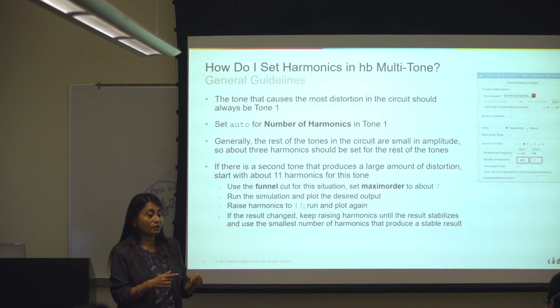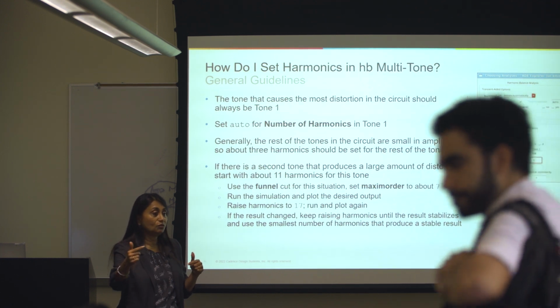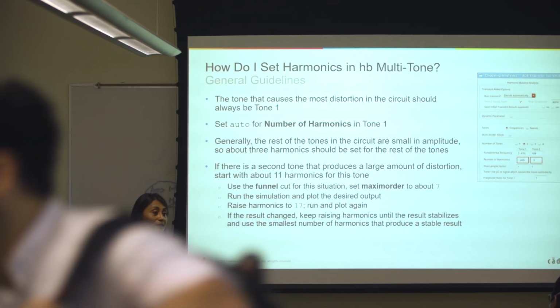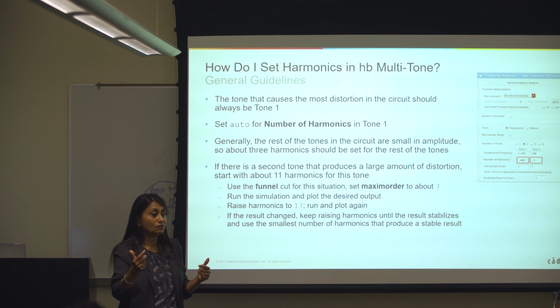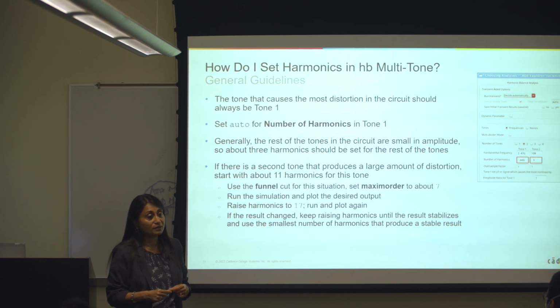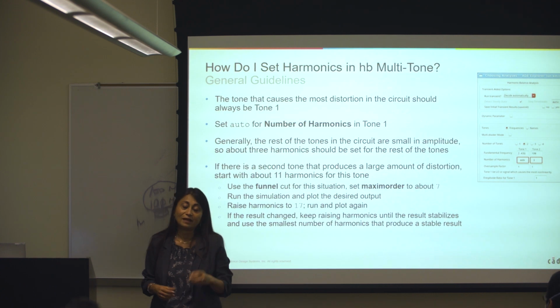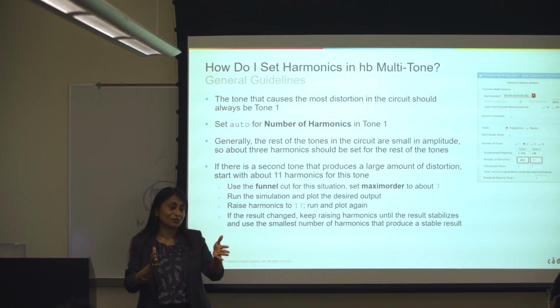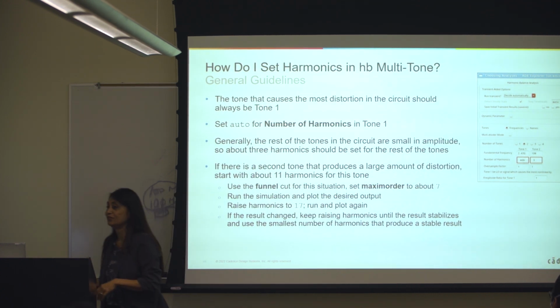If you're going to see your S parameter from LO to IF, your LO is at 1 gig, your RF is at 900 meg, so your IF is at 100 meg. So port 1 and port 2 are at different frequencies. That's when you need periodic S parameters, because that will take into account frequency translation. This is not directly related, but since you brought it up, I thought I'd mention it.